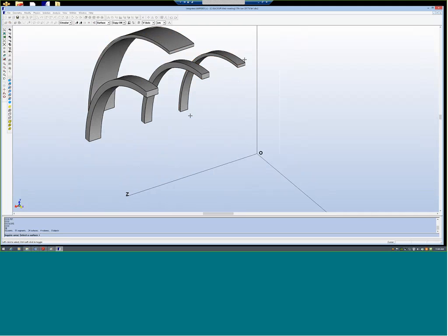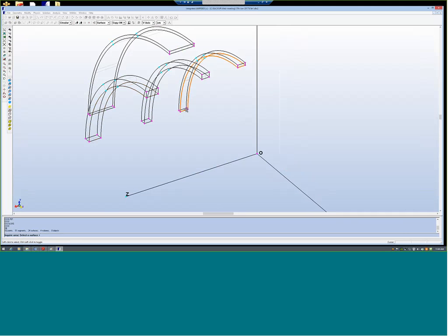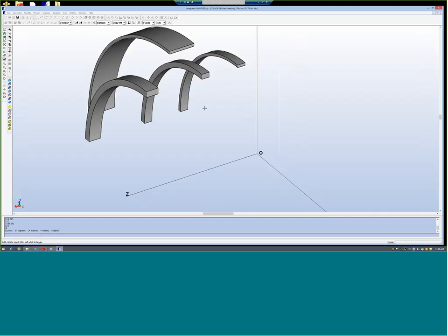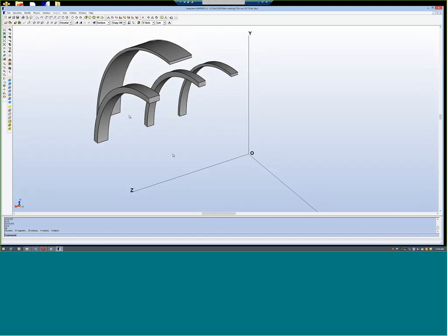Similarly, on the other side 5, and the bottom 6. The 6 surfaces are there. That is a must. Whenever you want to assign a current to any volume, it has to be 6 surfaced. That is the reason why I swept circularly for 90 degrees. I could have swept 180 degrees, but there is a purpose why I put only 90 degrees. You will understand once I complete the problem.